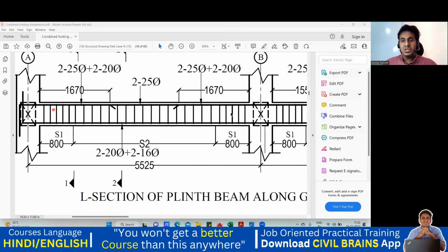So these are the junctions we have. This is a beam and column junction. Here the plastic hinges will be formed. These are the places where plastic hinges will form, where it will experience maximum shear force. I don't want this beam column junction to have a brittle failure. When I say brittle, it means it suddenly fails, and I don't want that junction to fail suddenly. So that is the reason we provide more reinforcement near the beam column junctions. This is according to earthquake theory, and for the same reason we provide it in this way.